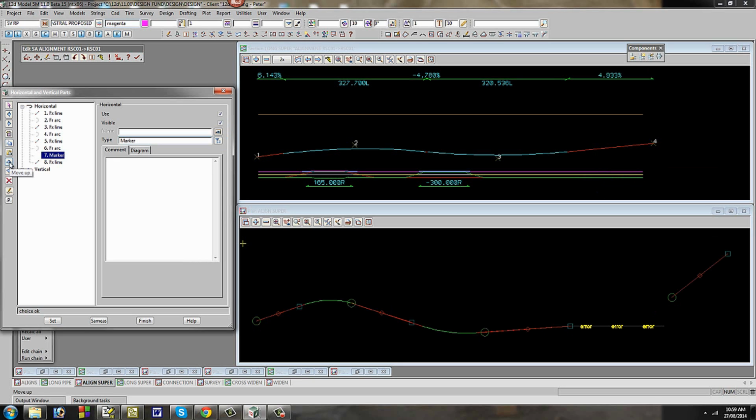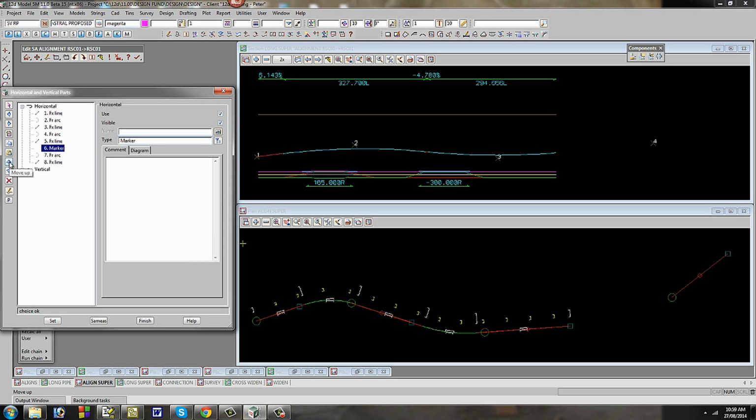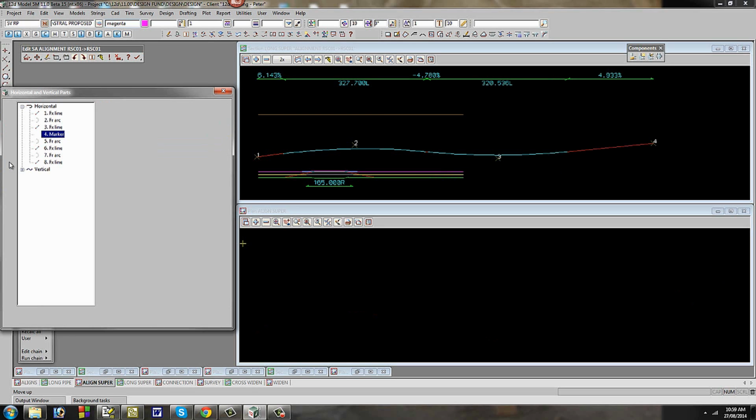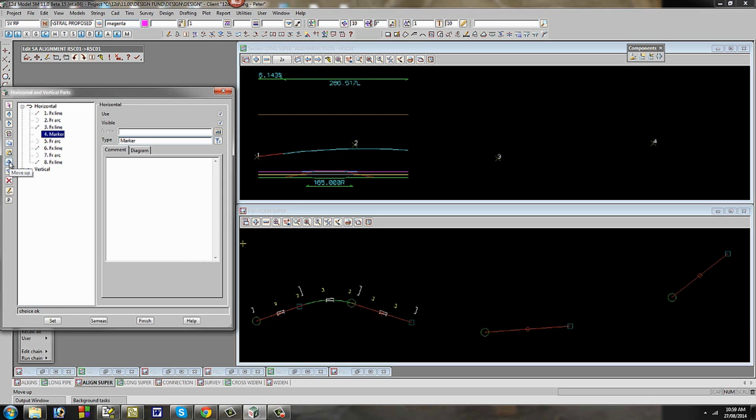As you can see here, if I position the marker above the last fixed line, it is not included in the solution, and as a result, the free arc fails. As I move the marker further up, you can see when the alignment solves, and when it does not. This is a great tool for analysing some very long rail alignments, for example.